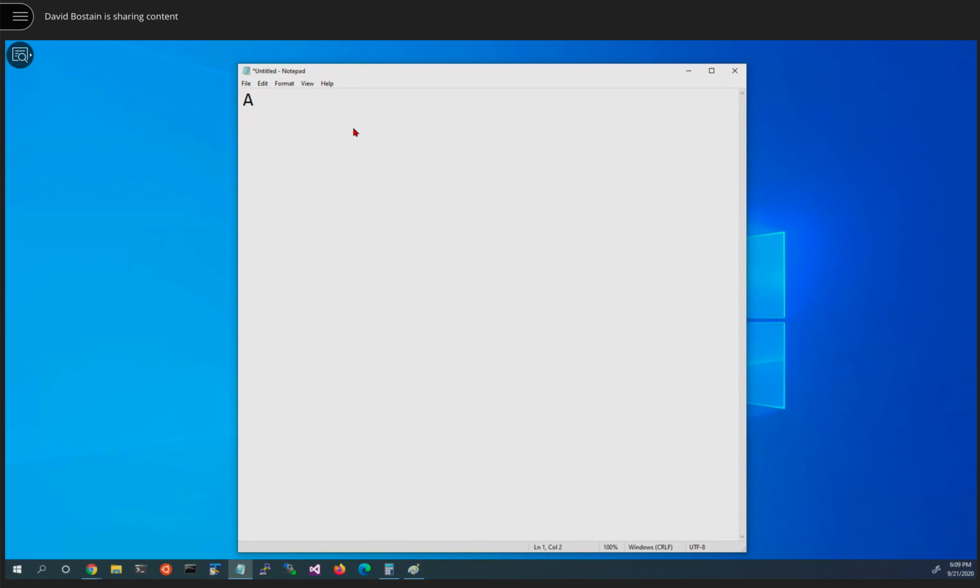I'm going to label the inputs, maybe A, B, C, D, maybe just A and B, maybe just A, maybe A, B, C, maybe I've got a whole bunch of inputs. Well, I'm going to start with a 2-input truth table, and I'm going to yield one output. Now, here's the notion of how these tables are looked at. In the columns labeled A and B, we consider those to be the inputs of a particular Boolean algebra function. And depending on how those inputs are arranged, we'll produce an output, which we label Y in this case, that will be invariant given those 2 inputs.